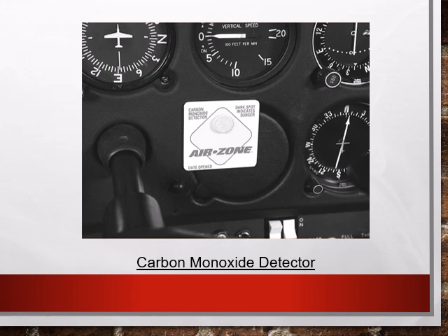Carbon monoxide detectors are critical, especially in piston-powered aircraft. These indicators alert pilots to dangerous concentrations early enough to prevent incapacitation. This type of carbon monoxide detector consists of a tablet that changes color when exposed to carbon monoxide.